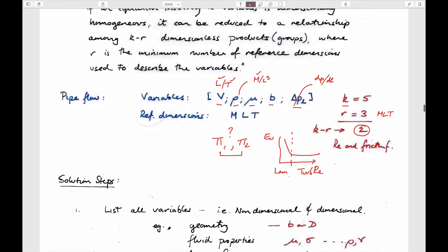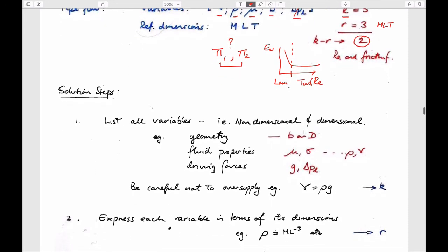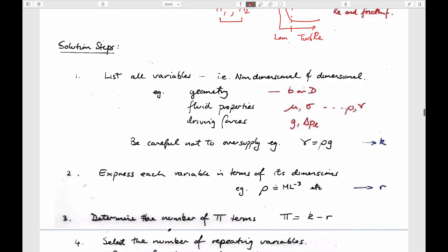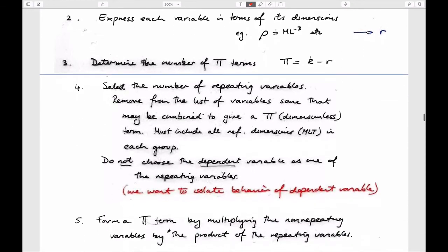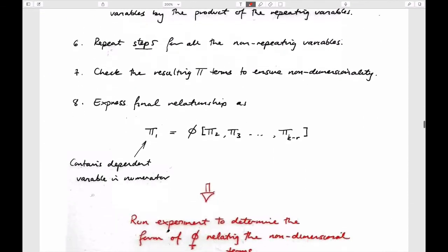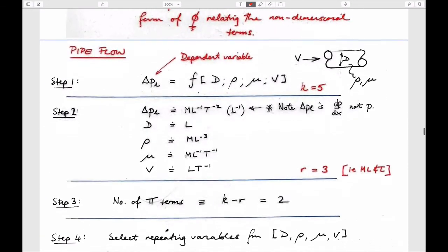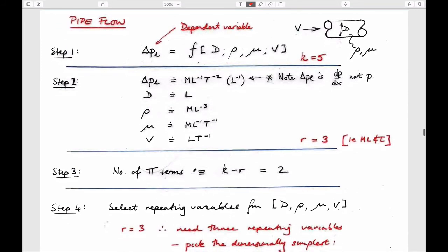And so the key then is to be able to figure out exactly how we are able to evaluate these non-dimensional variables. And so there's a formalism to it, and that is that we skip down through here. I'm just going to go through an example because you've seen this before. But if you look at pipe flow, for instance, where we have the diameter. We had B up above, but that's not right. The density, the viscosity of the fluid, and the velocity, and the pressure gradient along the length of the pipe that drives it. So again, 1, 2, 3, 4, 5 variables.